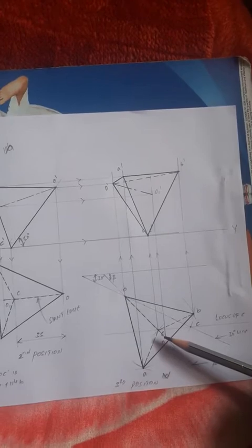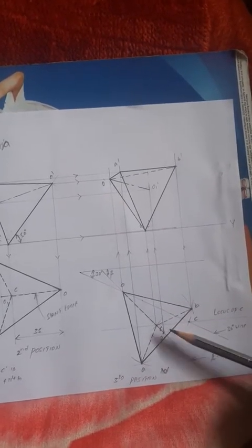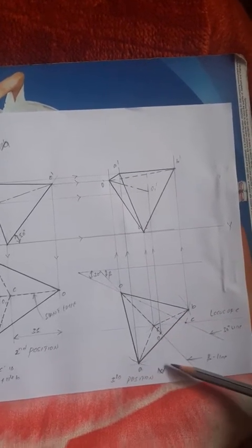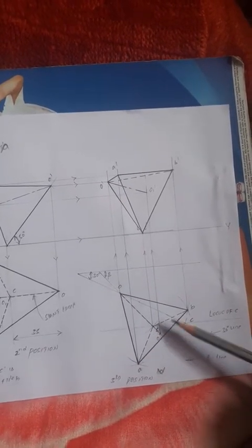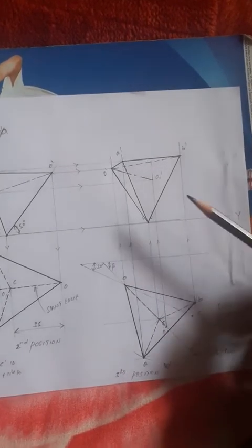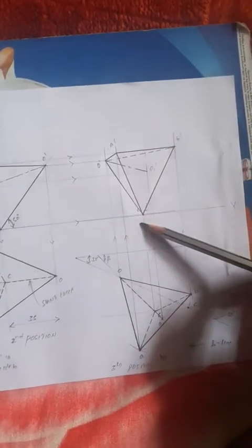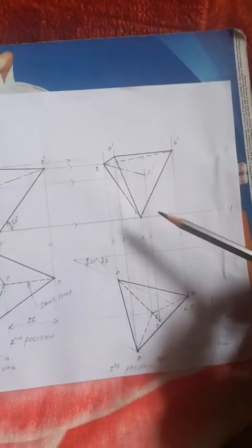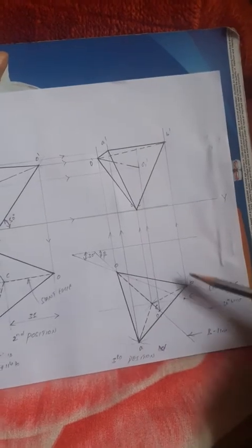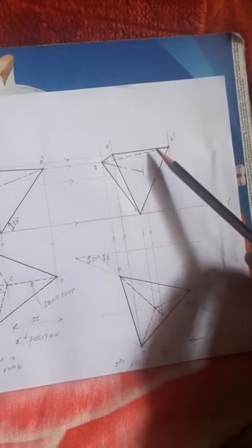Nearer to the observer. Then comes to see the B and C. From these two corners, which corner is nearer to the observer? C is near to the observer, right? The corner C is near to the observer compared to the corner B. Now the edge formed from A to C is visible, that's why it is a continuous thick line. Then O dash B dash, the B is away from the observer, O is also away from the observer, that is a dashed thick line. Then show the axis line. Yes. Now that completes problem number 44. That completes module 4, solids.